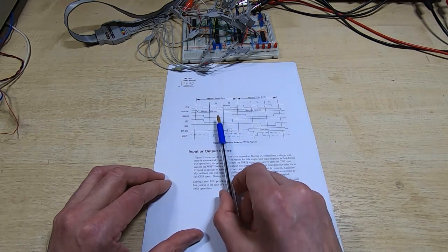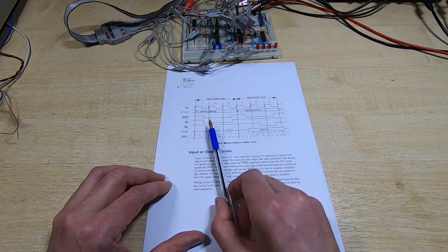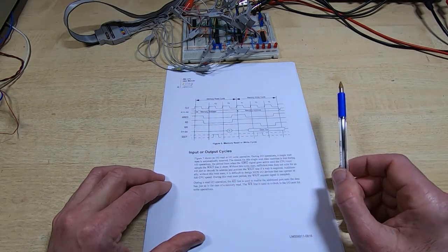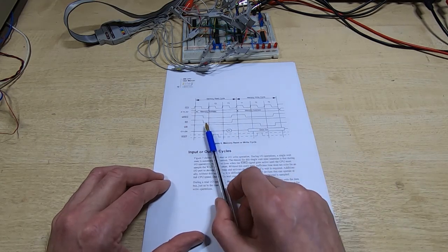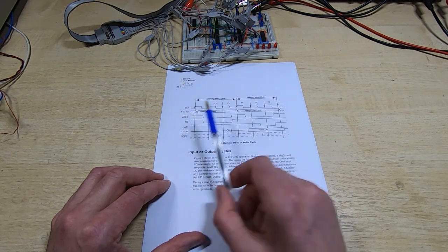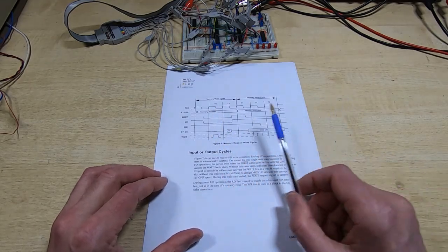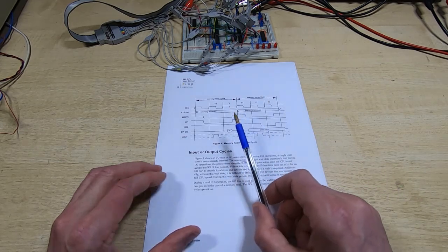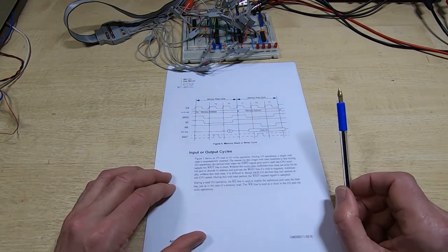The other thing of course is these control lines that we'll be making use of, we have to release when we're not using the DMA system. That's when the Z80 has not granted us access to the data and address bus, so we have to use tri-state buffers between our DMA control system and the control lines, and the same with the address bus and the data bus. We can't just leave our system inactive. We need to make sure it's actually disconnected as far as trying to drive those circuits is concerned.